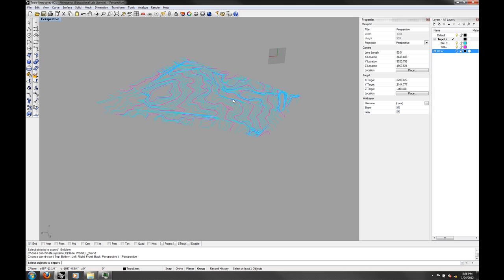For those of you who know anything about 3D, you might ask why we don't loft these things together. A loft is when you take two or more curves and stretch a surface across them. We'll talk about this later in the class, but a loft won't work here because of the complexity of the contours. Some contours occupy the same height but are in different locations, so it's not possible to stretch a loft over it. So what we're going to do is this patch.